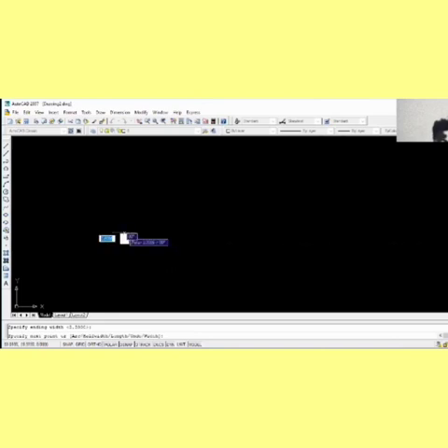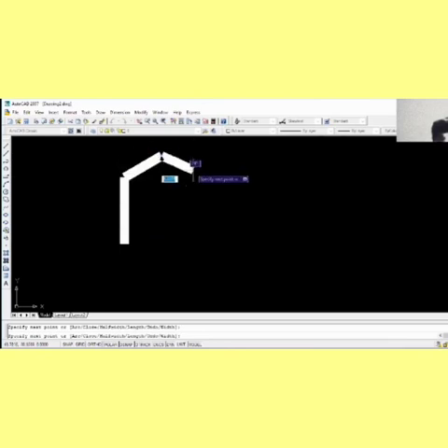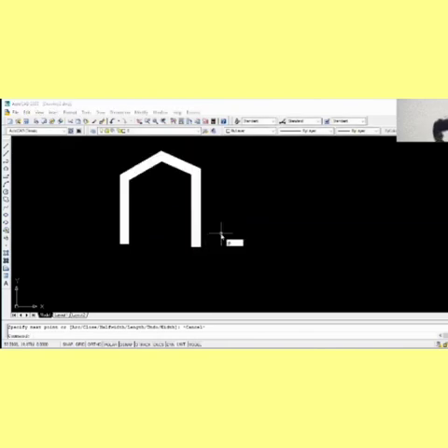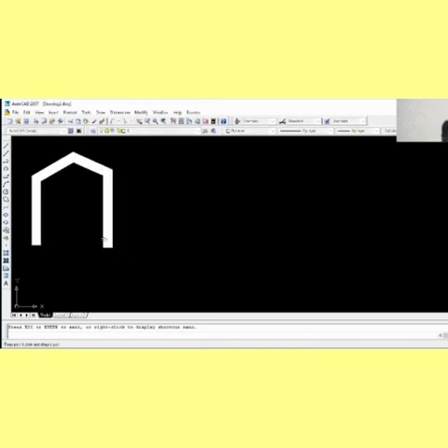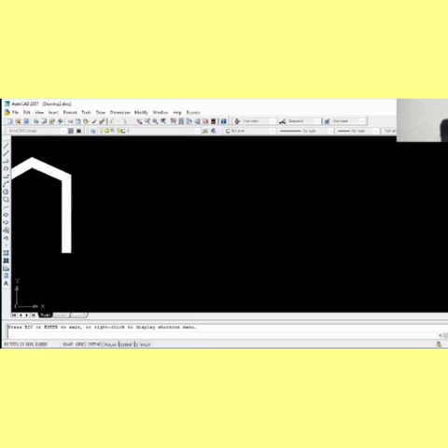So now you can see that the width of the line has increased. So I can move like this. I can create a shape that I want. I can move like this, and then I can move this way. So that's exactly what your polyline does. And then you press escape. So you use your P pan to move it to the left. P enter.